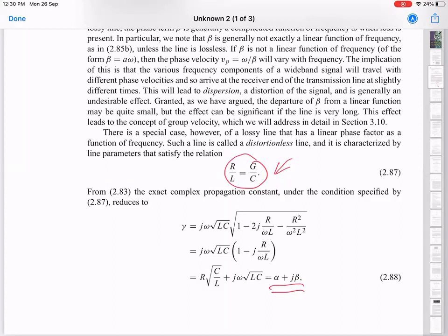So it almost necessitates that any such signal has to go through a bunch of losses, so that by the time it reaches the low temperature, the room temperature noise is almost completely eliminated. And you're dominated by the noise corresponding to that temperature and the components which are there, so the Johnson and Nyquist noise. This is a very technical aspect of cryogenic experiments, and I will be discussing some of these examples in a lot more detail at a later stage. But that's what I meant.